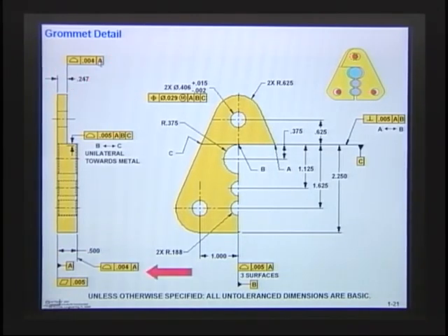All right, the next thing that I did was on the bottom here, you see I located where this surface is, and I said that had to be profiled within 4. I'm contacting on a datum surface, and then that surface has to fall within a band of 4. So basically, what is it? It's kind of like 500 plus or minus 2. But the plus or minus 2 doesn't come from a datum. This one here says establish the datum, come from the high points, and make sure that surface falls within a band. So I use profile.